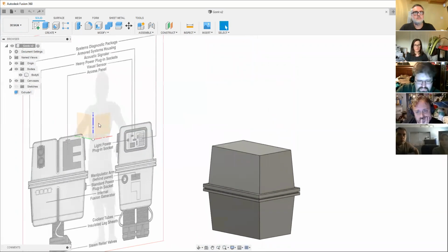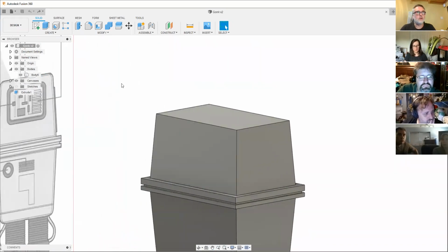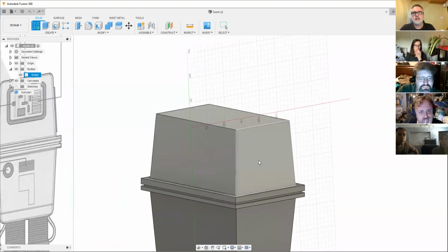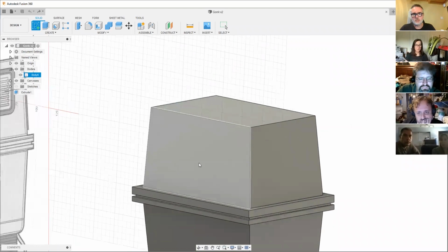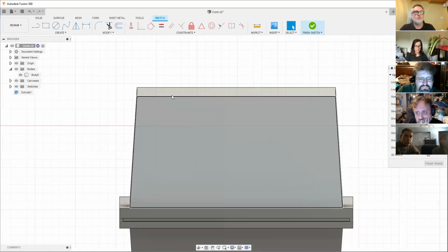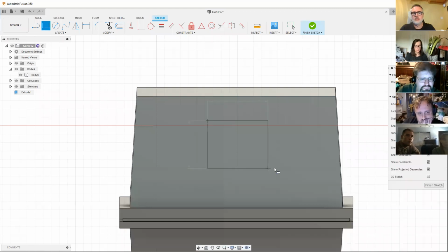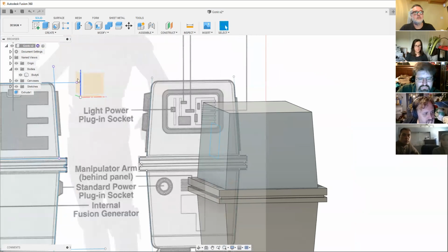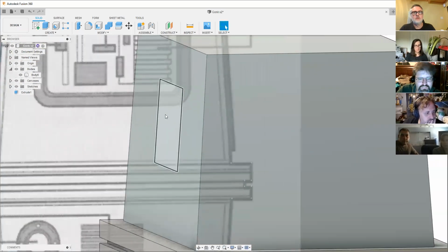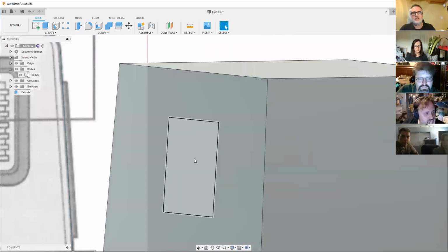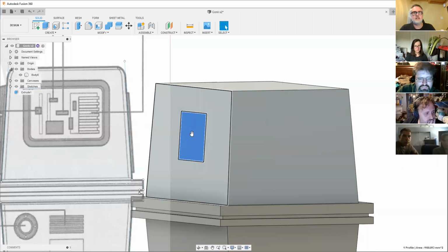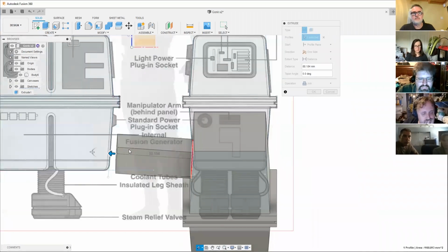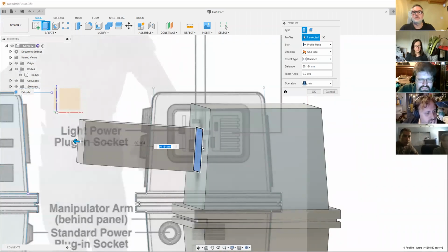So as well as drawing on these backdrops and extruding a square or a shape, if you go into draw mode and select any of these planes, so if we wanted to put some detail on the side, what you can do is then draw something actually on that flat plane on the model. I'll show you what that does. So before, you only had 3 different aspects to be able to draw on. What we've done now, if you can see, is drawn a square actually on that plane, which means that if we then extrude it, it comes out at the same angle as the plane of that body, if that makes sense.